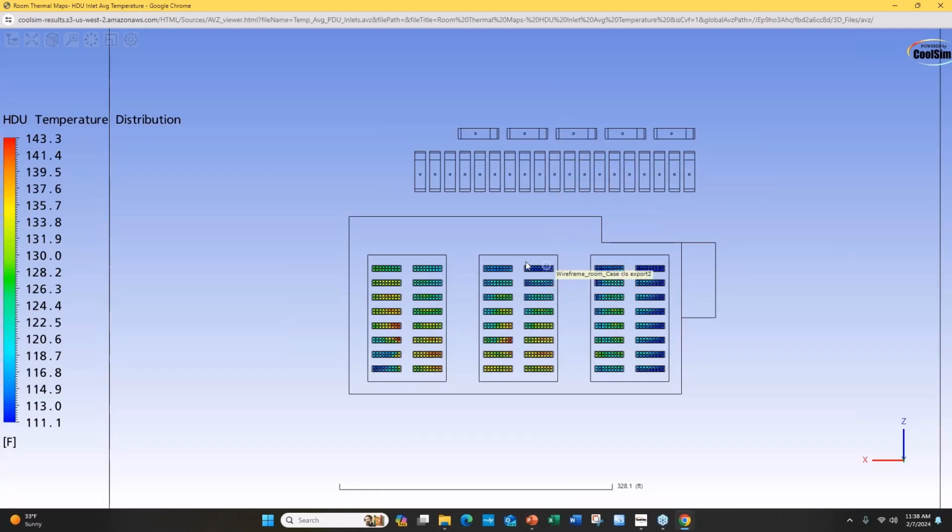Do these generators contaminate these heat exchangers under a wind that's coming from the top side? That would be a study you want to do. To redo a study, all you need to do is just reset the model, change the wind directions, and resubmit it. Turnaround times on these models tend to be a couple hours. I was turning this one around in 2 hours, so that's not too bad.